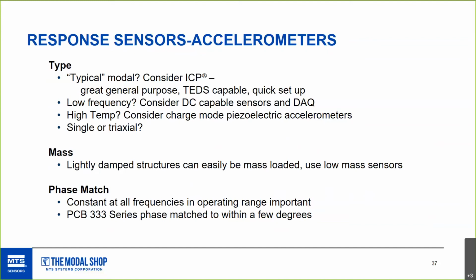And like Chad alluded to earlier in the presentation, consider using dummy masses. Test your object on certain key parts with or without that mass, or put two accelerometers on and see if your data looks different than with one. You can start to get the idea of the effects of mass loading.